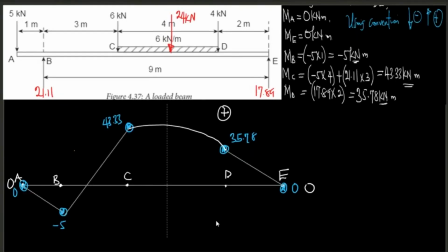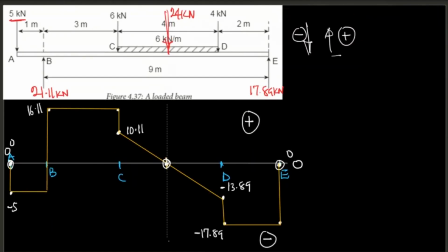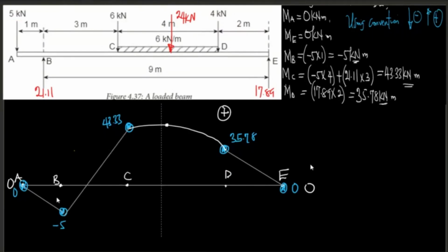And you see, the point of maximum bending is not 43.3, it is actually at this point. You can see it's a bit of a curve that goes up. It's because of my hand, it's just a hand sketch. The point of maximum is just a bit here. You have to make sure that this straight line is drawn onto the bending moment diagram.